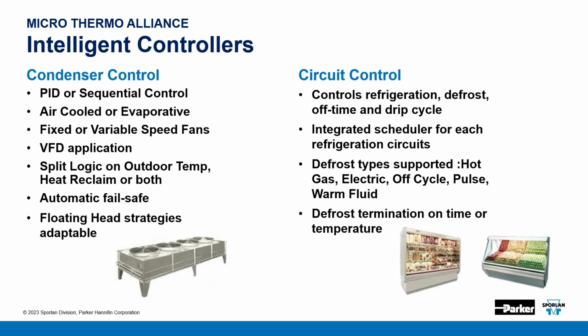As far as condenser or gas cooler control, we could do PID or sequential control. It can be air-cooled or evaporative, fixed or variable speed fans, VFD applications. We can split the logic based on outdoor temp or heat reclaim. Again, there's an automatic fail-safe on board and floating head strategies, which are adaptable.